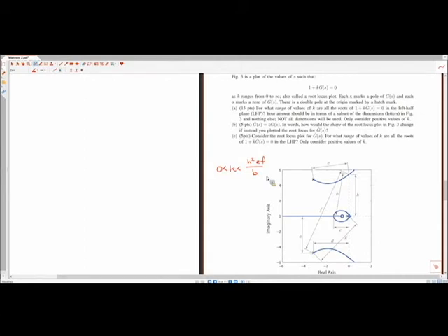Because K causes the system to go unstable when any of those poles crosses the real axis, or crosses the zero axis of the right-hand side. So there's a really convenient point on the upper branch where there's a bunch of nice, happy vector magnitudes marked out for you. Right there? Yeah. So you have vectors from the double pole at roughly the origin.